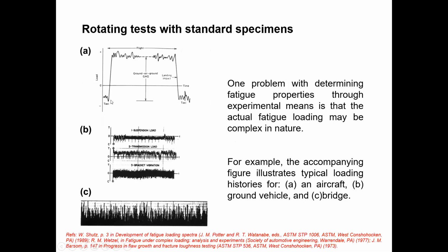You can see that when it takes off, is in the air, and lands, the stress varies in a very complex manner. You can't find a simple sinusoidal type of stress variation here. So you need to deconvolute this type of stresses to find out the fatigue lifetime. And this is